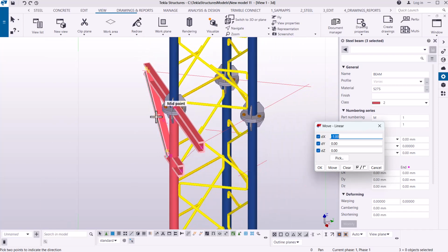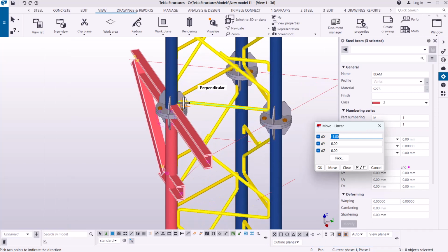So in this section, you have to consider the position and the direction of the z-axis. You can see at the bottom end here, y is facing that side and the x is facing us. So what I'm going to do is feed a dimension in the direction of y, but we'll prefix that dimension with a negative sign because we are moving in the opposite direction of the y-axis.